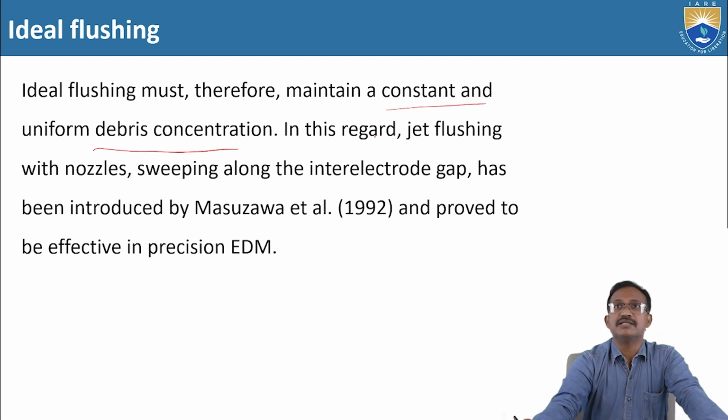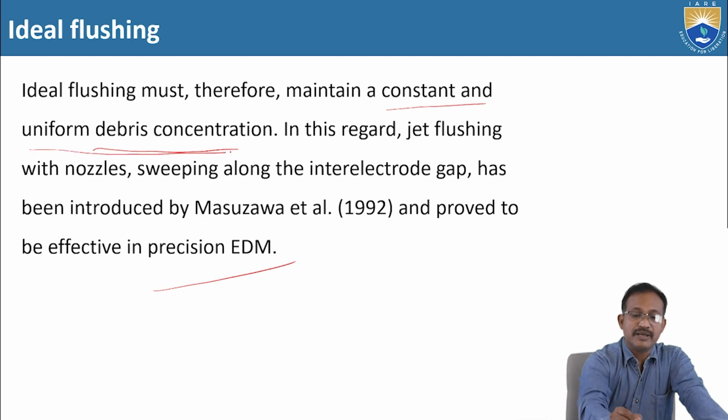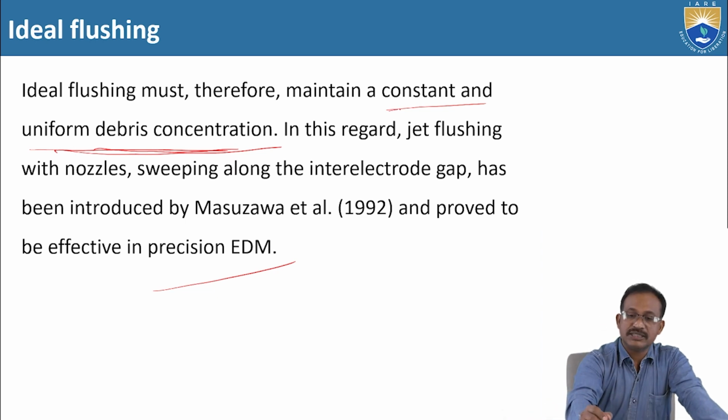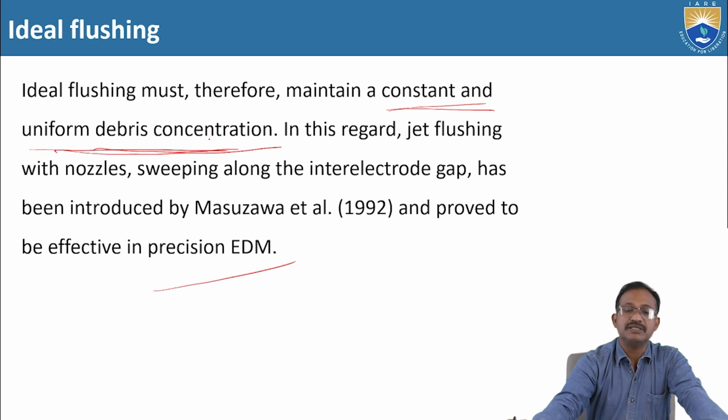In this regard, jet flushing with nozzles sweeping along the inter-electrode gap was introduced by Masuzawa et al. during 1992 and proved to be effective in precision EDM. So here uniform debris concentration is the important one.